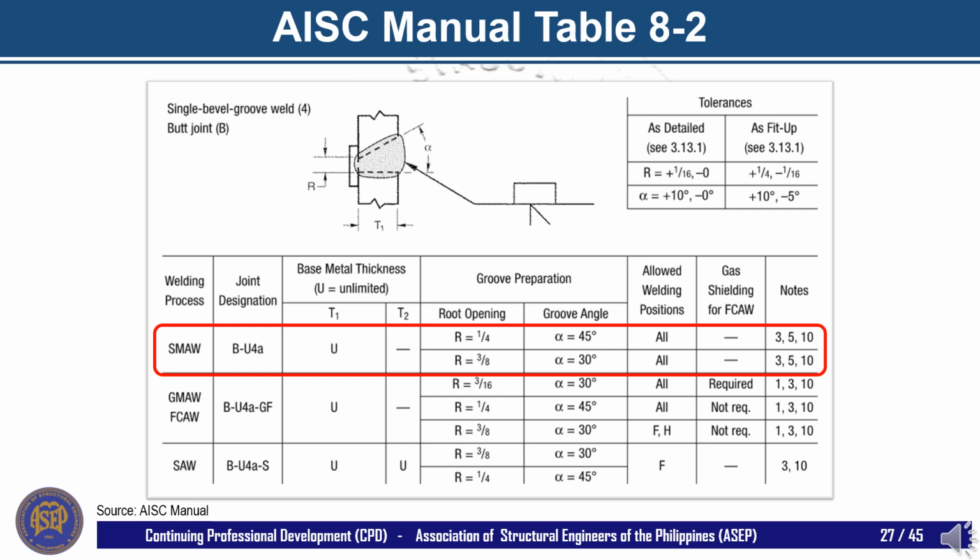Table 8-2 of the Steel Manual, also found in AWS D1.1, gives a number of pre-qualified CJP welded joint details. The tables provide joint geometries such as root openings, angles, and clearances that will permit the deposition of a sound weld material.